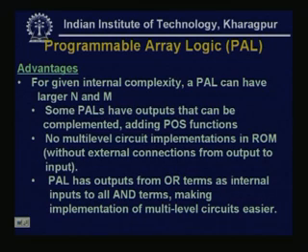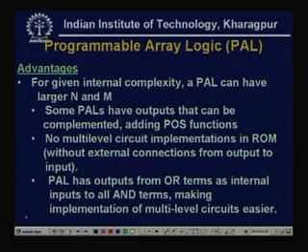As it is a fixed OR plane, in the design itself the larger value of M can be selected. Some PALs have outputs that can be complemented, adding POS functions. So, this is a very important property.